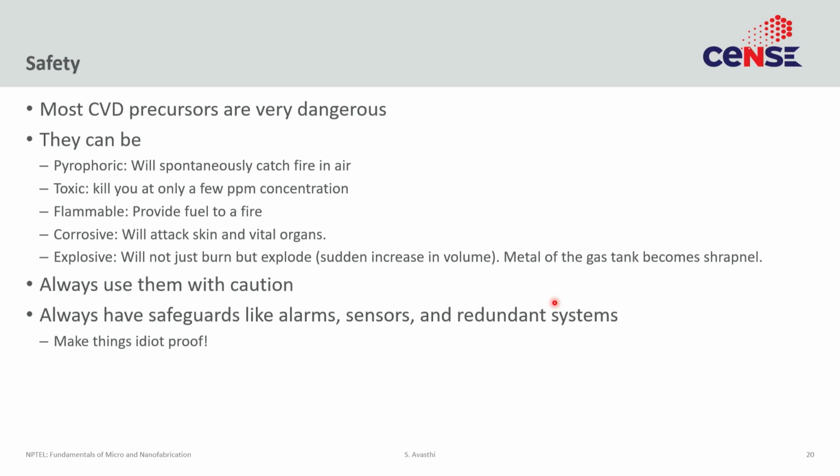They are toxic, pyrophoric, they can kill you, they will cause explosions, they will attack the stainless steel, they will attack the cylinders that they are contained in. And a lot of these things are both environmental dangers, but also personal life and safety dangers. So always treat precursors with extreme amounts of caution. If you are new to them, please talk to somebody who has experience in dealing with them. Industry has a lot of standards on how to manage these types of gases, and we should follow them.